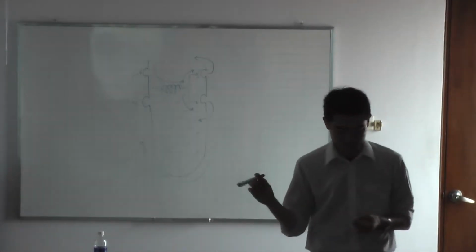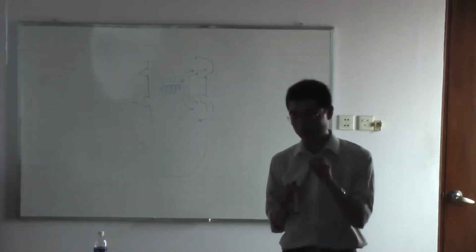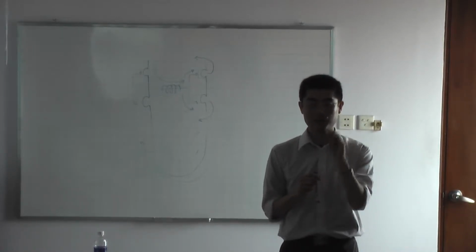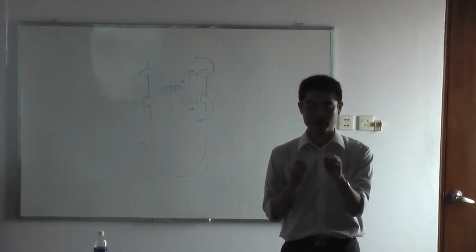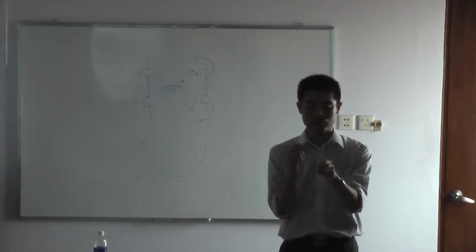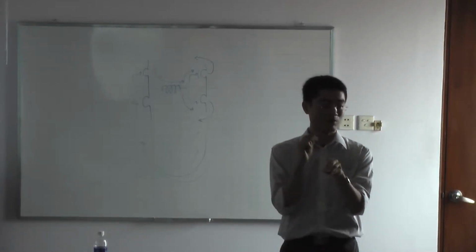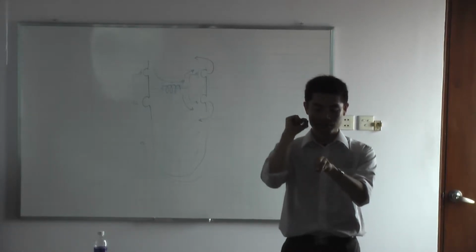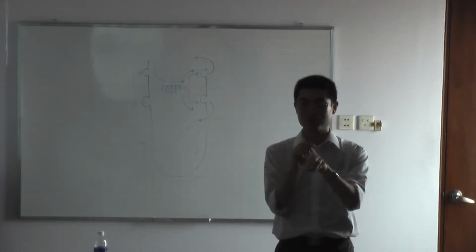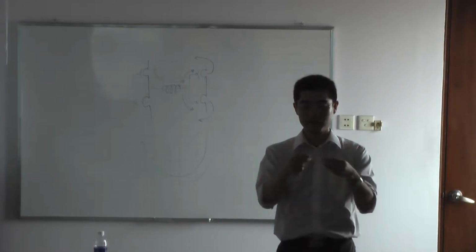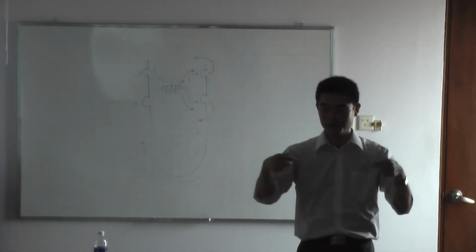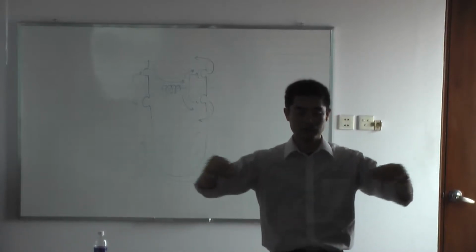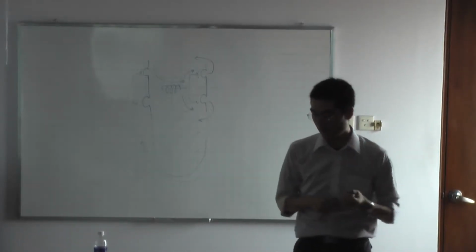And here, the power splitter. In the power splitter, the input impedance also has to be 50 ohm. Otherwise, we will have reflection on the terminals, and we don't want reflection to happen. So the input impedance from the input node should be 50 ohm. And from the output terminals, we will use 50 ohm SMA cables.